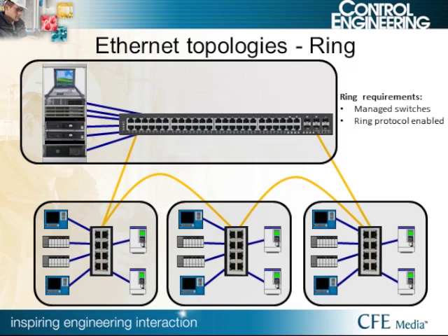If we add fiber or copper cables between the panels, we can create a ring. So if one of the cables, connectors, or Ethernet ports fail within that ring, the network traffic will still pass over the redundant link that we put in. There are a few rules that need to be followed with redundant Ethernet connections.